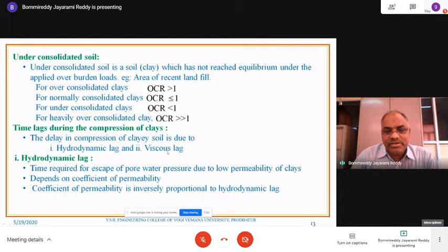When the soil is completely in plastic state and the viscosity of the soil particles is more, and all the soil particles are surrounded by a lubricant type of water, then such soils are called viscous soil. Once the soil is in viscous state, deformation takes place, called the shear deformation.